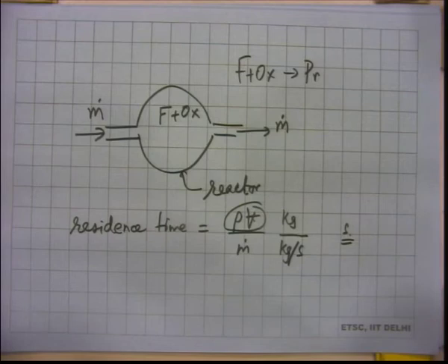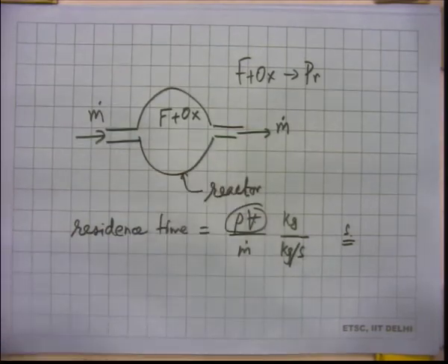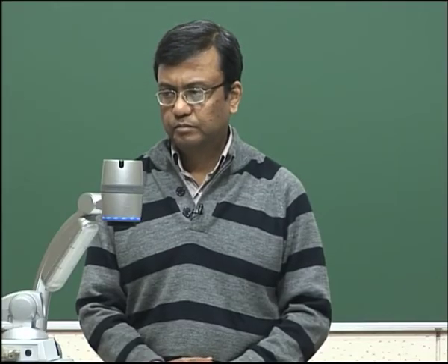So, even though we discussed a simplified model, of course, a gas turbine is not well stirred, in the sense that it is not uniform composition inside, and it is not the same reaction rate everywhere and things like that. But from a simplified perspective, we can understand that if you push the reactants too fast, maybe the rate of reaction will get affected, because the residence time is too small. Maybe reactions will not happen properly. Yeah. Can we say like this, if the residence time is very much less than the chemical time scale, then reaction will not occur? Yeah.